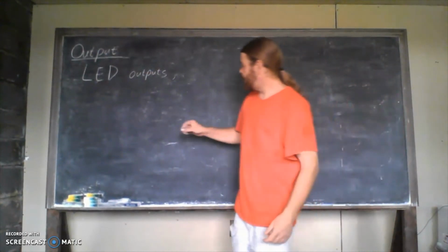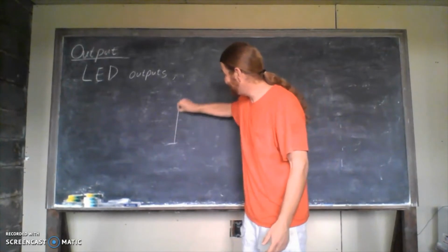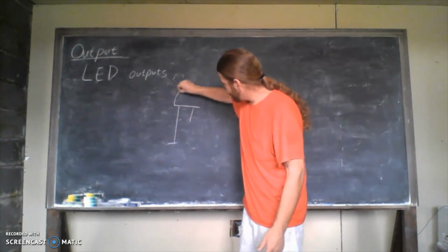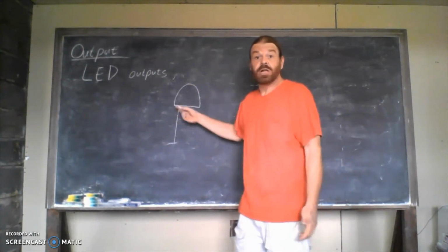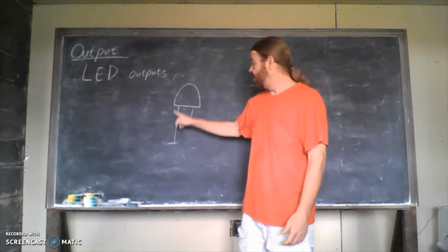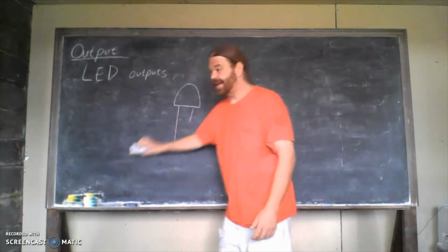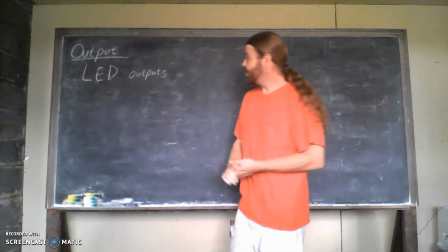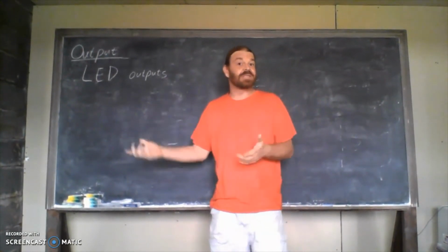And I think I forgot to mention a minute ago, I specifically drew the picture that way to say something about it and then forgot. Unless they've been trimmed, if you just have a simple LED, just a basic single color on or off, one of the leads will be longer than the other. The longer lead is the anode. I drew that picture to say that, and I think I forgot to mention it. So, but we don't always have to use the simplest LED.